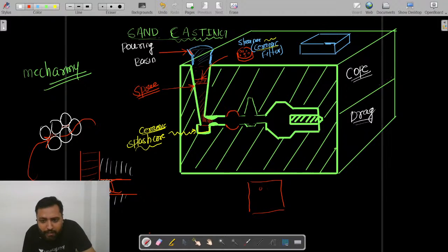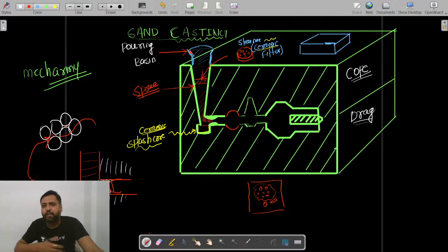You will find these small cavities, which can be spherical or elongated in size. These are gaseous defects: blowholes can form, blisters can form, pinhole porosity can appear. These are all gaseous defects that occur due to the entrapment of air particles, vapor, burnt gases inside the casting.